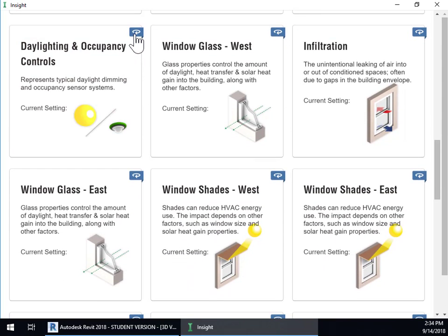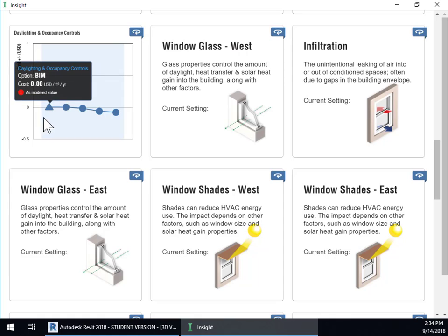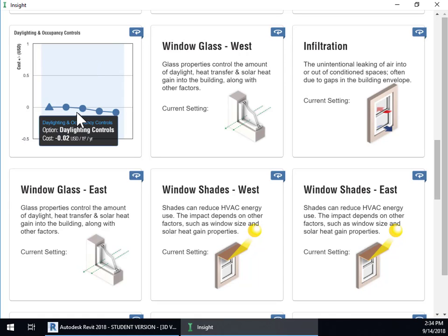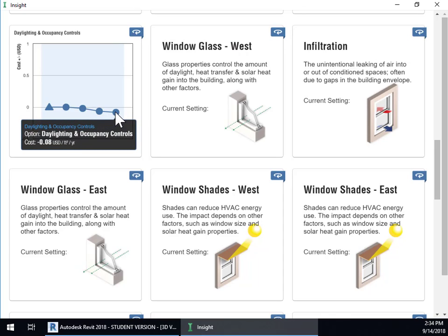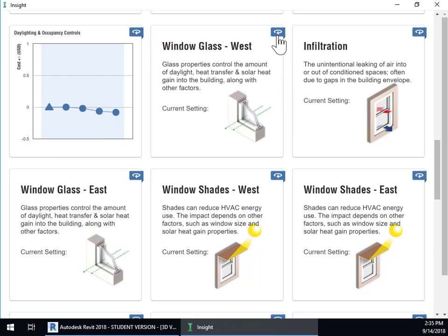And then daylighting, okay. We could introduce daylighting. I think we could even have greater impact if we had just daylighting controls. Here they're just talking about daylighting controls, not even optimizing the daylighting itself, just saying, if we have adequate daylight, then dim the lights or turn them off, as well as occupancy control. So you can see we can get another 8 cents there.